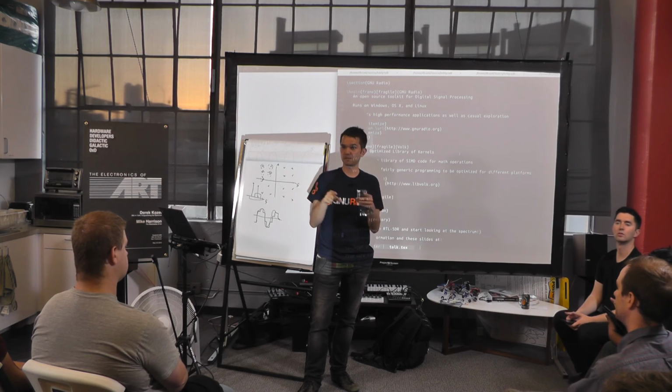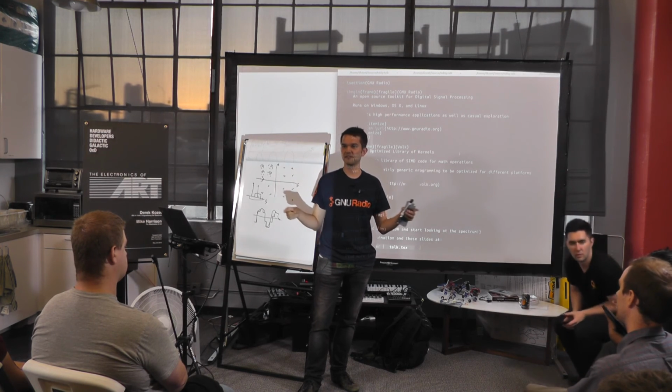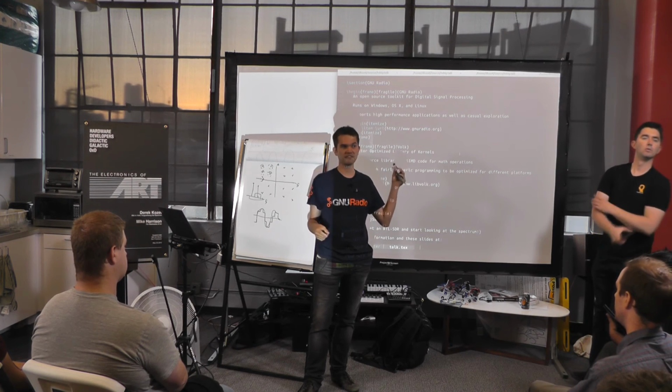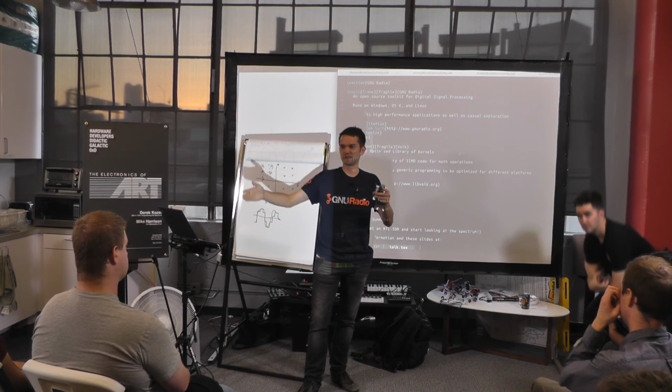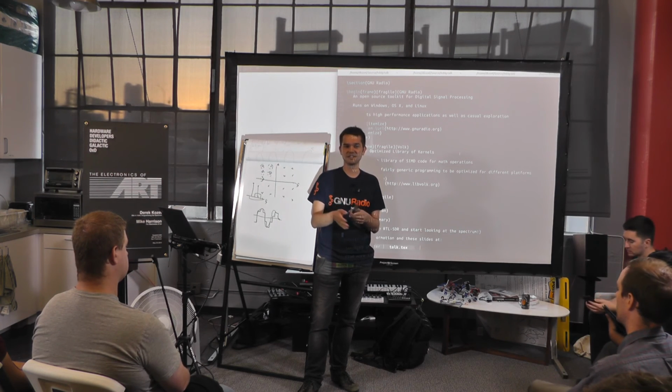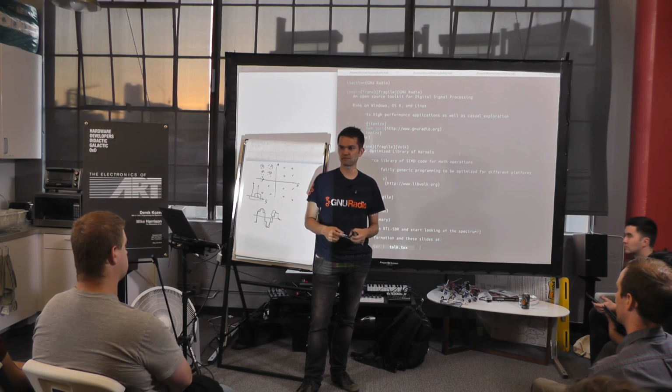So if you want to send more data fairly easily, then you need a wider and wider signal. If you have a 20 megahertz wide Wi-Fi signal and you put it down at 10 megahertz, you take up everything from DC to 20 megahertz, which is a huge amount of communications at the moment. So they shoved that up at 2.4 gigahertz, where there's just free room for days.